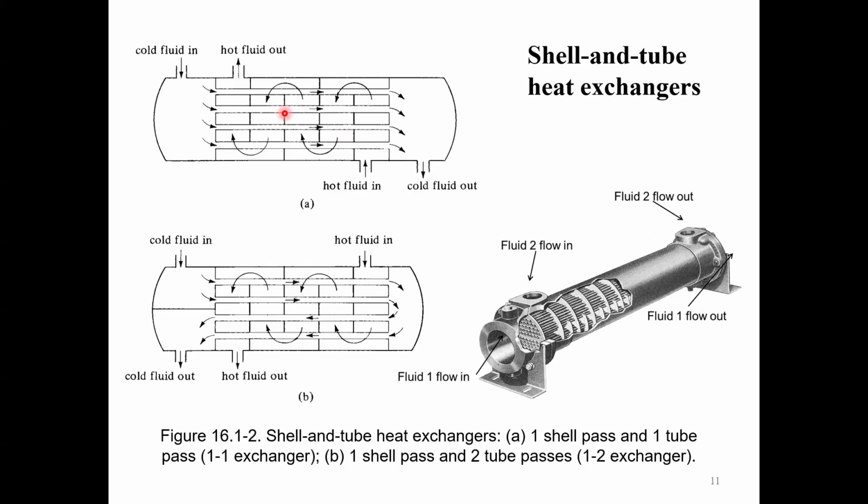Not only that, it also allows the shell side fluid to take passes across the entire heat exchanger. If you don't have baffles, you could imagine the fluid will take the shortest path to the exit. Then you will form a lot of dead zones. To avoid those dead zones, you introduce these baffles.